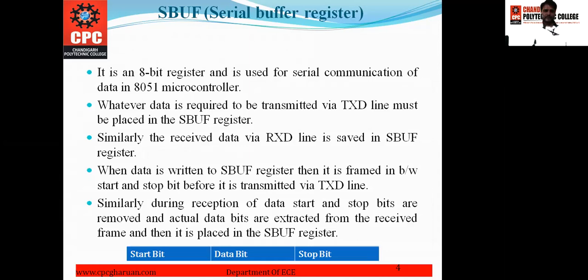Now we will discuss the serial buffer register, that is the SBUF. Its main function is to store the data to be transmitted before transmission and to store the received data before it is read at the receiver end. It is an 8-bit register used for serial communication of data in the 8051 microcontroller.